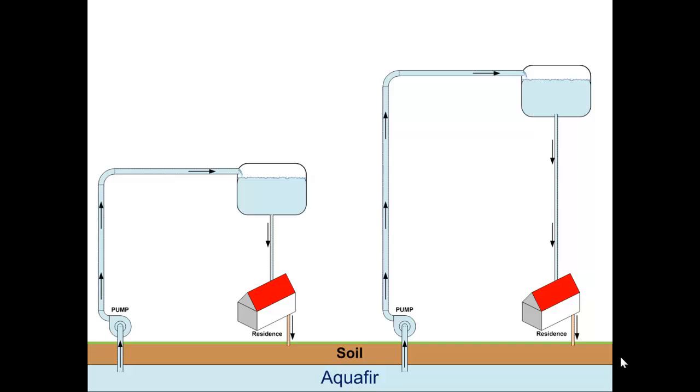And when we have public power, because the power goes off every day, we have an electrically powered pump that pumps water from the cistern underground to a tank up on the roof of the house. And we have a float switch inside of that tank that turns the pump on if the water level drops. So usually what happens, the power goes out every day and you keep using the water. The instant the power comes back on, the pump kicks on, it pumps water up there.